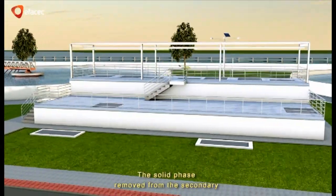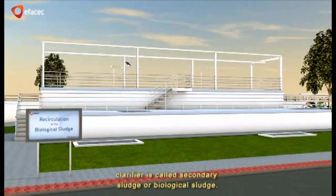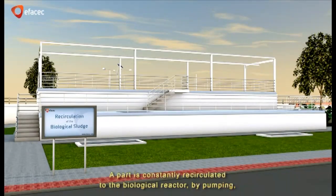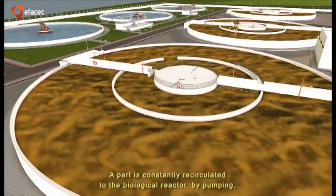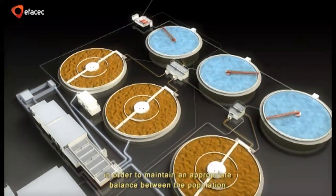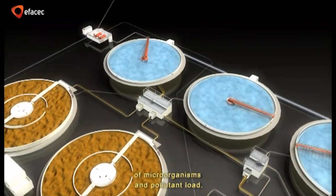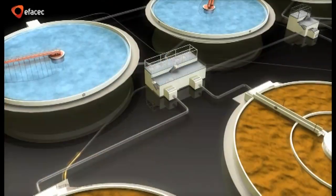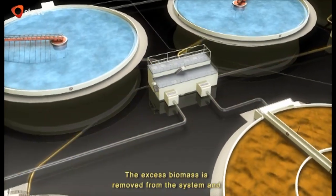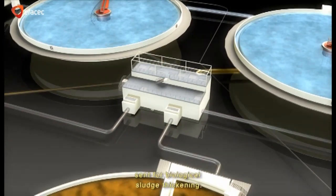The solid phase removed from the secondary clarifier is called secondary sludge or biological sludge. A part is constantly recirculated to the biological reactor by pumping in order to maintain an appropriate balance between the population of microorganisms and the pollutant load. The excess biomass is removed from the system and sent for biological sludge thickening.